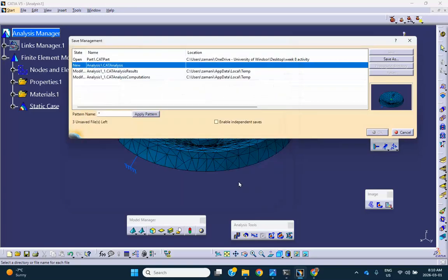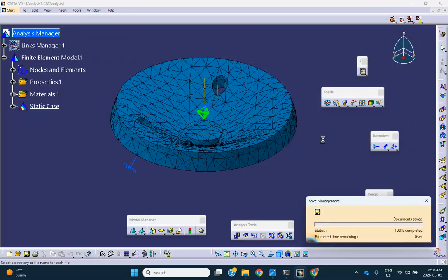and then save. But this is critical. Say propagate directory because I want everything, including a copy of that part that was saved already, go into this folder, full model activity 2. Don't forget propagate directory. Notice that they're all going in there, and then you say okay.